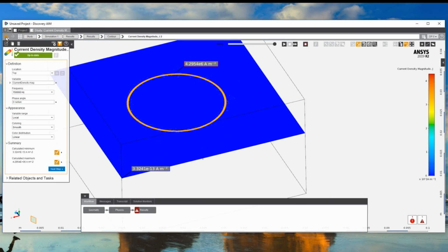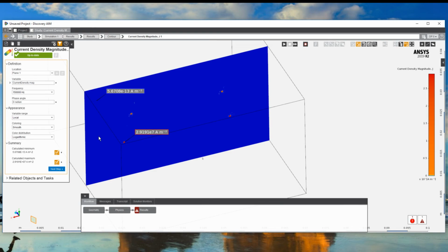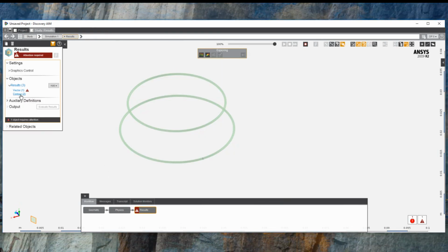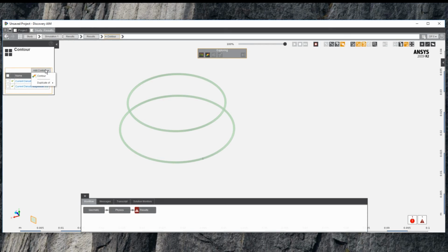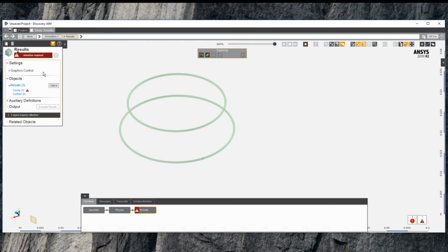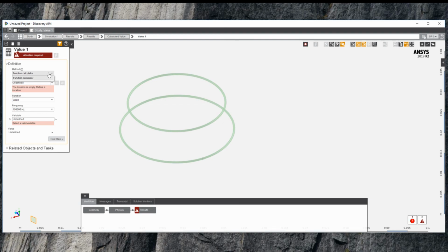And oh, one more thing I need to mention is you can do that functional calculation. So here, calculate the value. So you can pick a function, and here pick a location and select the value. We can look at the loss, total loss, core loss, and any loss, and you can calculate the loss value from the coil.